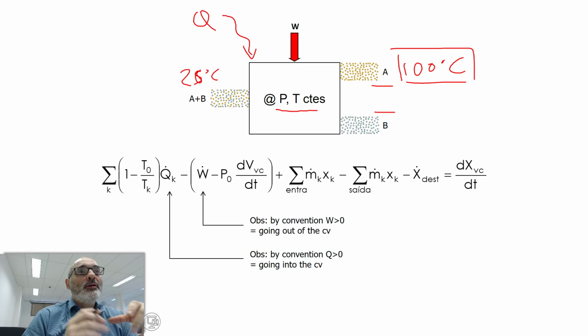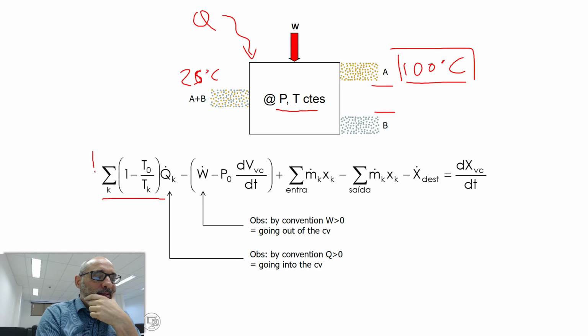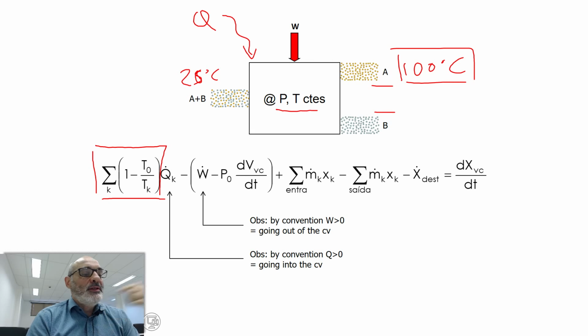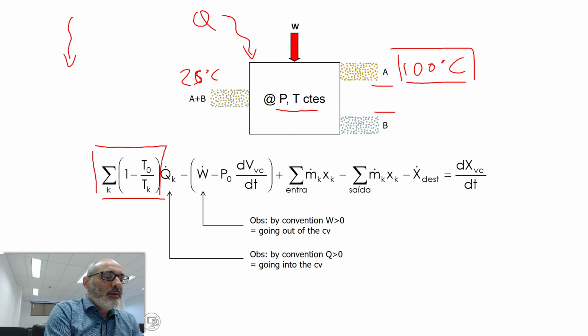It's not 100% exergy, it's, I don't know, 75, 50% exergy. And this amount of exergy we can calculate by multiplying it by a Carnot efficiency. Because the idea is that you take the same amount of heat and use it to drive a Carnot machine, okay?